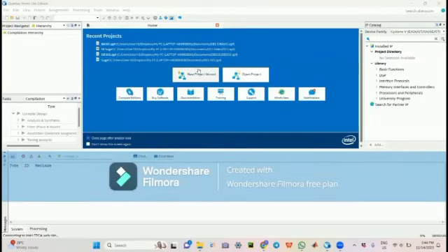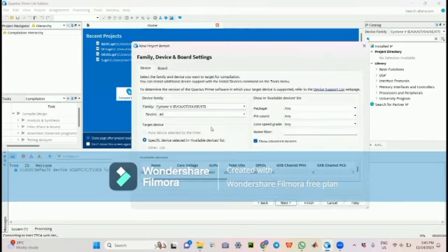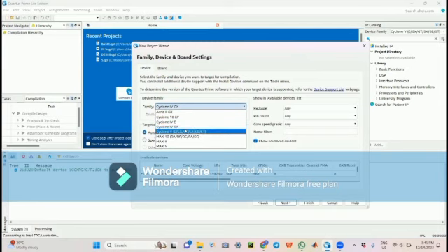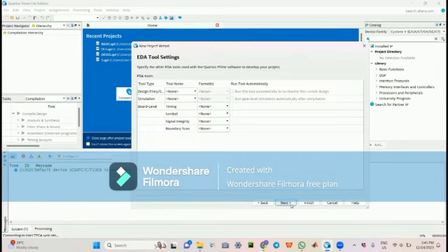I'm Tan Cha Sing and I'm here to show how to use the Intel Quartus Prime software to realize and simulate our project design. Firstly, we need to create a new project. And then in here, we need to choose the Cyclone IV GX as our device family, as the Cyclone V cannot support the timing simulations to simulate our project. And then we just press finish.